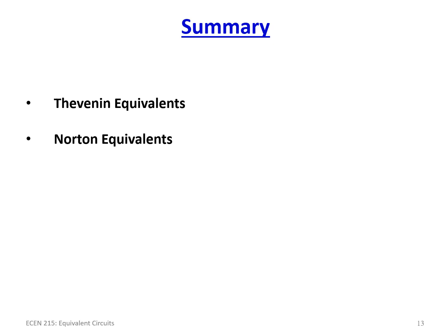So turning it into a two-component circuit. As such, we also talked about what the load would be to enable maximum power transfer. Because of the series resistance in the case of the Thevenin equivalent, you would have to have the load resistor equal to the series RT for there to be a maximum power transfer, or the parallel RT in the case of the Norton equivalent.